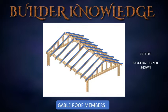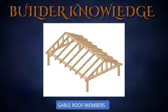Rafters. The common rafter extends from the plate to the ridge at right angles to both. It supports the main body of the roof and is usually spaced 16 to 48 inches apart. The barge rafter is the same as a common rafter except that it has no bird's mouth and is found on the overhang at the rake of a gable roof.